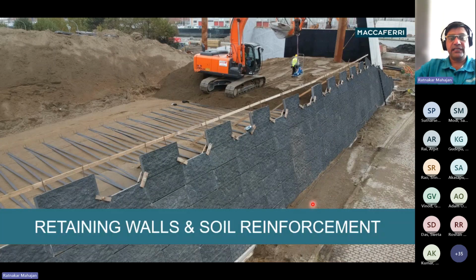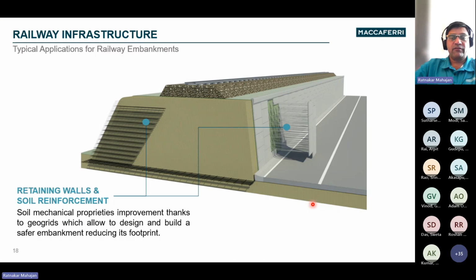Now, after understanding soil erosion, let's move forward to the other application, that is retaining walls and soil reinforcement. For every problem, the right solution, that's the requirement. The reinforced soil slopes or walls are very flexible structures. In our portfolio, we deal with wraparound geogrid structures and our Paramesh, Terramesh with gabion facing and Green Terramesh structures combined with high-strength geogrids of Paralink and Paragrid, up to the vertical walls of Macres. Vertical walls Macres are reinforced with high-strength geostrip, which we call Paraweb.